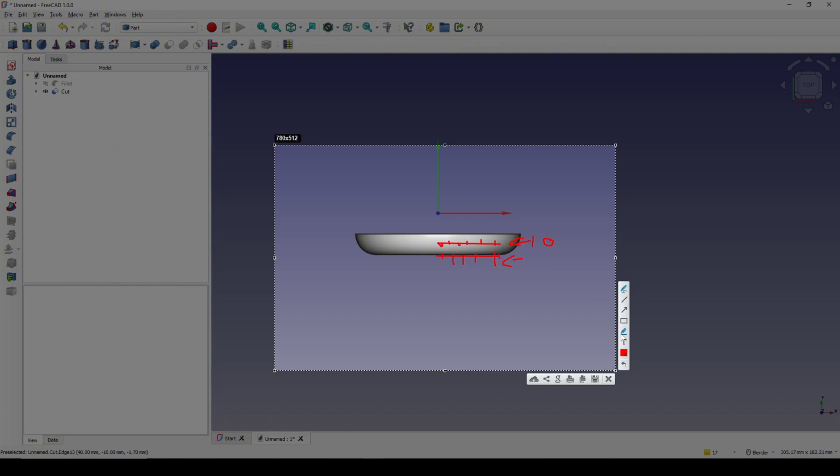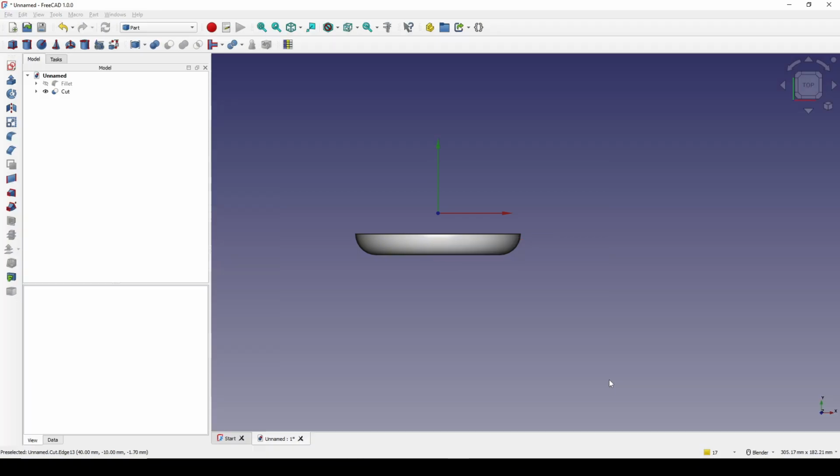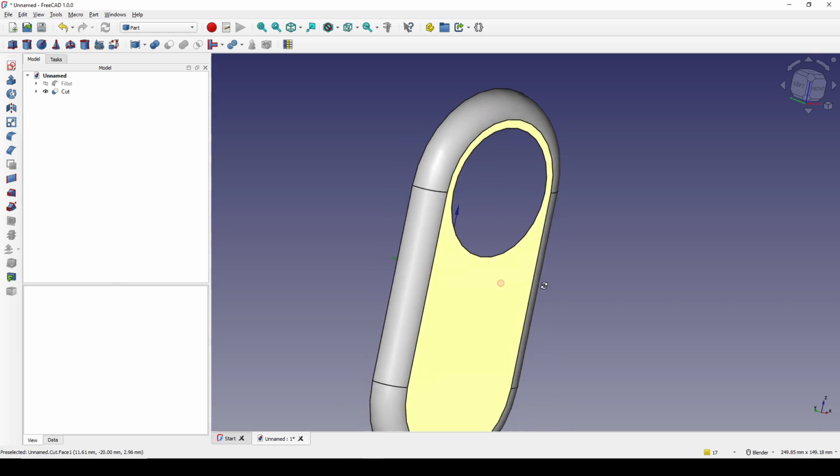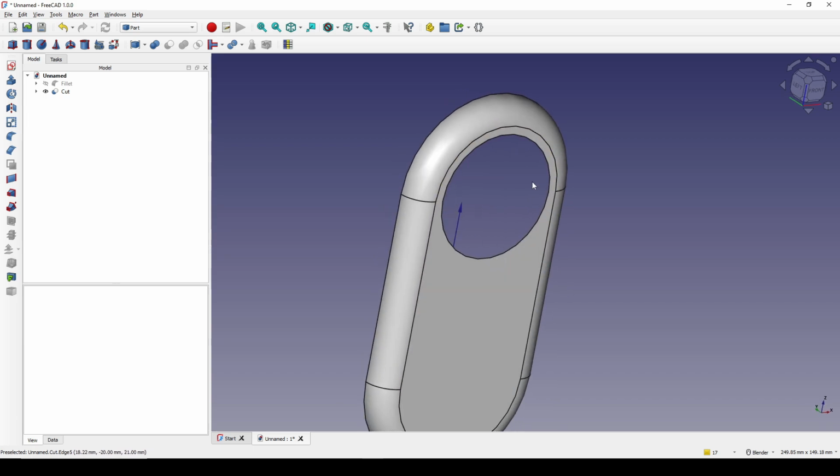And in between, I will generate a sketch to connect like a zigzag curve to generate a sine curve connecting in between. And when I have this sine curve, I will use this sine curve to sweep or revolve around one axis to generate the surface.